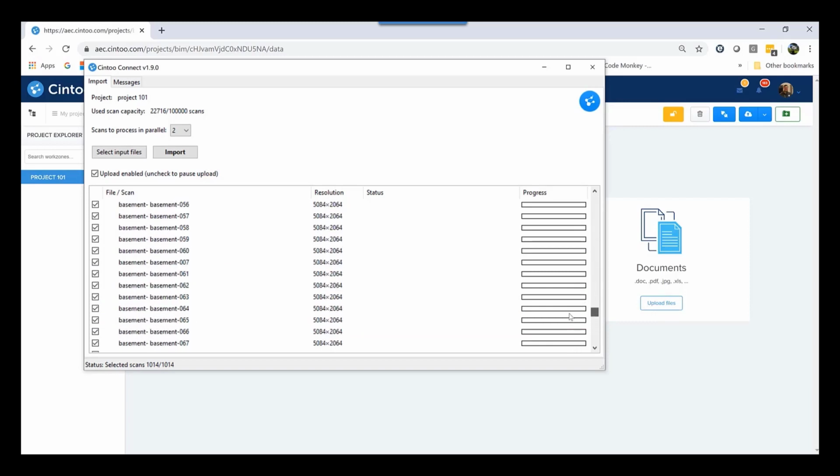And you notice how I label my scans. I tell it's the basement, 4th floor, 3rd, 1st floor, arcade, whatever the location is. I like to give it a name, and that plays an effect down the road when we're organizing our scans. You can either organize them by name, you can organize them by selecting them. On a busy site, the name is always the best way to go.